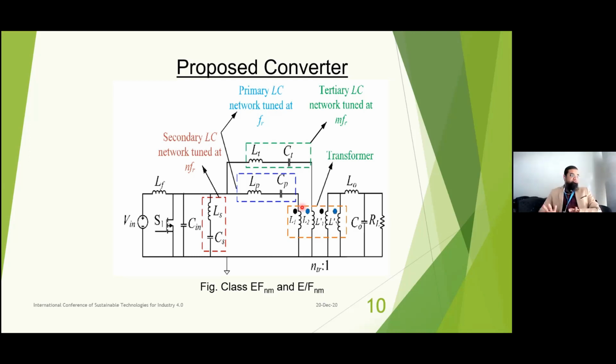Why a multi-winding transformer? Because it will be built on a single core. It will help us to reduce the size, to reduce the magnetic losses, and to make it compact. As I said before, it's a very low component count circuit. If we can reduce the transformer size, the total size of the converter will be very small. We have different applications, like laptops, chargers, and LED lighting, so we need to keep the size really small. This single core multi-winding transformer really helps us achieve this purpose.